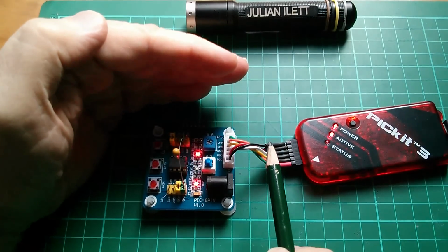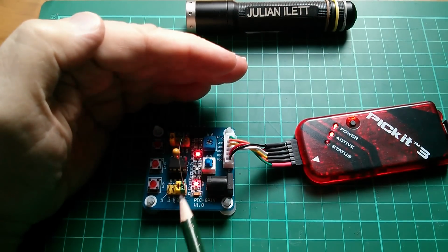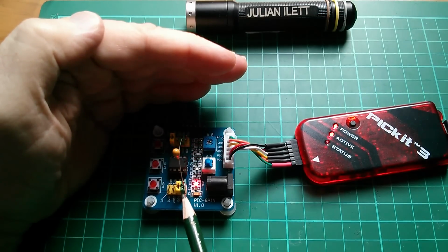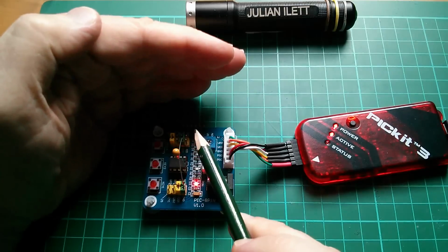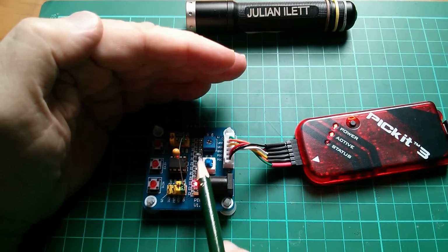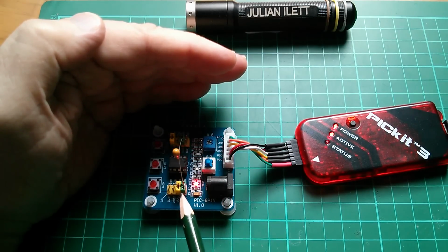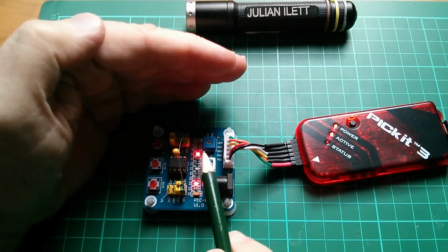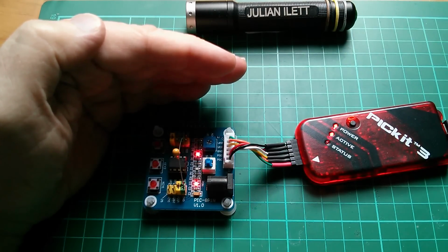So the software is doing exactly what we told it to do. It's turning the LED on with a bit clear. That actually lowers the value on GP0. It's then using a no-op as a delay. Now the clock is running so slowly because of this big capacitor that the no-op is actually quite a long delay. It's then turning the LED back off by raising the voltage on GP0, and then we loop round and do the whole thing over again.